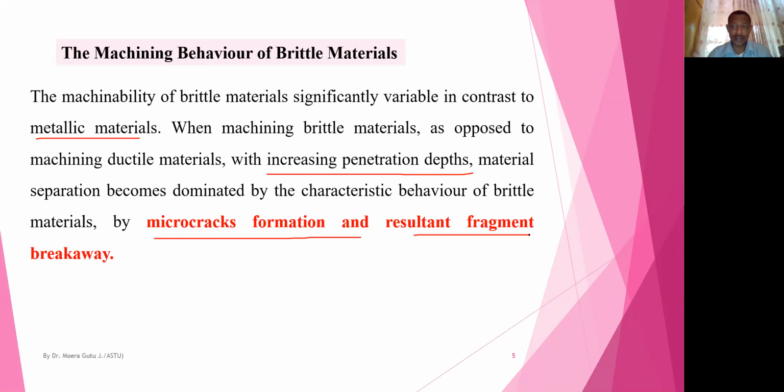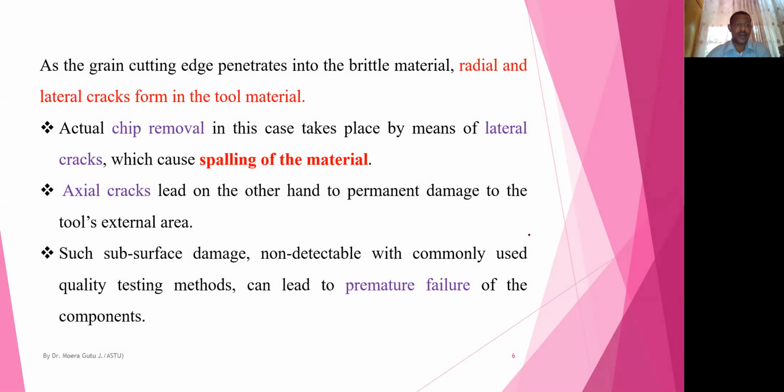So we have to approach machining of hard materials in such a way that the science and the features to apply to the cutting tools should be based on research. As the grain cutting edge penetrates into the brittle material, radial and lateral cracks form in the tool material.